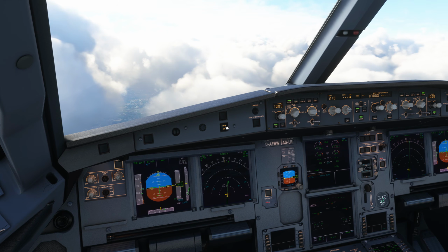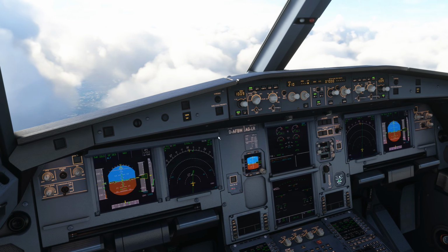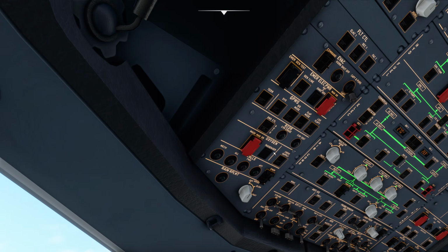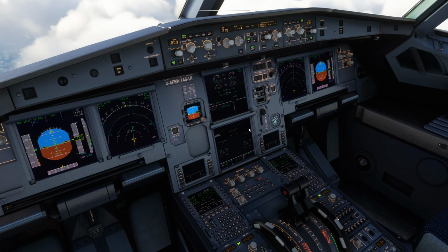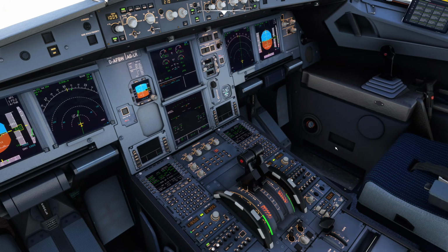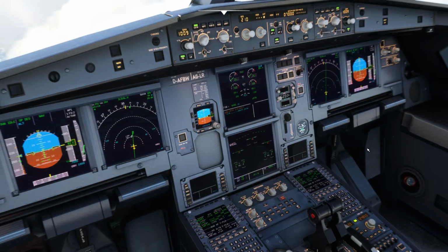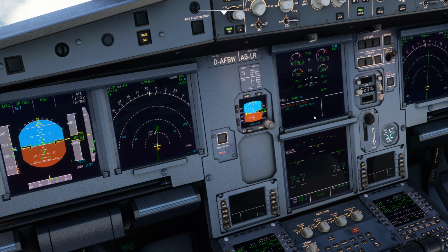Well, it's worth noting before you lower the landing gear with your gravity extension that the gear will not be able to be retracted. Once you've lowered it, that's it, it's down. As you saw earlier, there's a huge amount of drag with the landing gear down, so by doing that, you're going to have a huge fuel penalty. So we will be very careful with when we actually apply this. It says, for example, landing gear gravity extension.